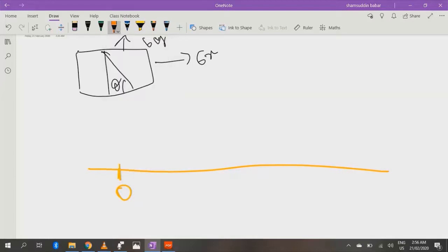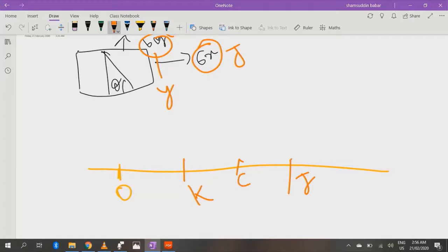In the x-axis direction we have the magnitude of stress x equal to OJ, and the magnitude of stress y equal to OK. So we have this point J and this point K. After that we will bisect at point C. Now this is our radius. This is our center C.